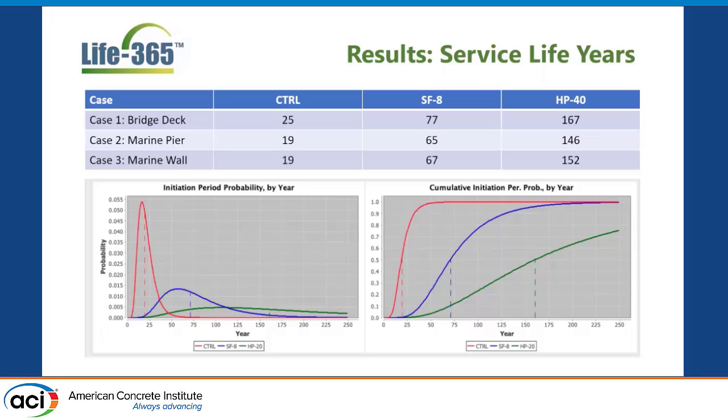Any other questions? Any other corrections? Maybe just an additional comment. I thought with Life-365 you have like 6 years later, the application version. Right, so you have the initiation rate. Neil explained the target for this session was to get 100 years of initiation time at a 90% confidence rate, so you are kind of excluding initiation time. Right, but I don't want people thinking it's all going to be 10% delaminated.